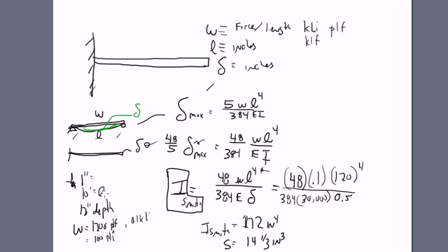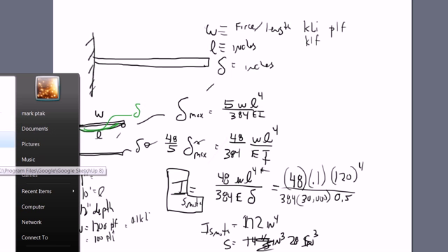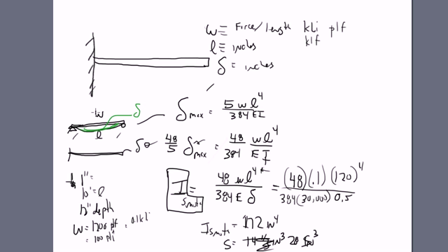and I'm incorrect there once again. That looked a little low. You don't divide by the full depth, you divide by the half depth, so in fact you wanted here 28 as a section modulus, inches to the 3rd power. So that, of course, you can go out to the web, and we'll try to do that while we're still rolling as we would here, and see what the heck's there.